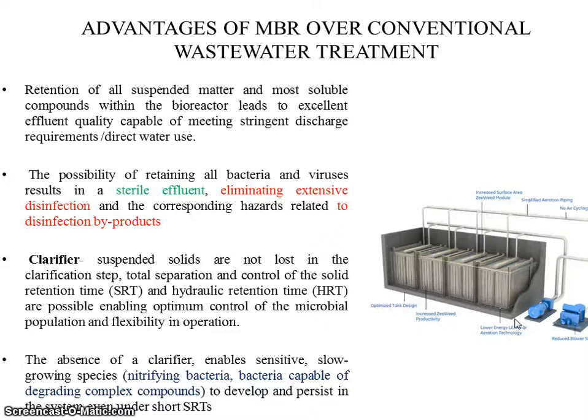And there are also certain advantages in operating environmental conditions such as HRT and SRT. Since you retain your solids for a longer time, you can have better control over the degradation of even the solids. Suspended solids are not lost in the clarification step, and total separation and control of the solid retention time and hydraulic retention time are possible, enabling optimum control of the microbial population and flexibility in operation. The absence of a clarifier enables sensitive and slow growing species, especially nitrifying bacteria, to develop and persist in the system.